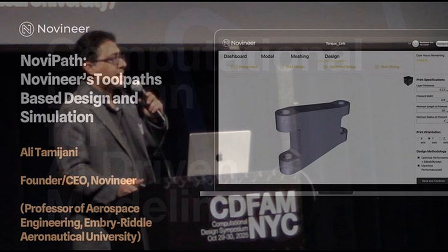And we mathematically proved this, and we showed how this works. So if you have the stress distribution inside your part, you can take derivatives, and then you can get those functions, and then you can draw them. Okay, great. Now you have load path. Probably the best thing you can do is put exactly the filament on those load paths, because they will make sure the load is transferred from point of application to point of support, as you will see in some examples. But there was a problem.